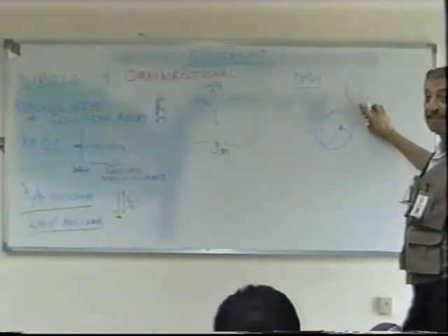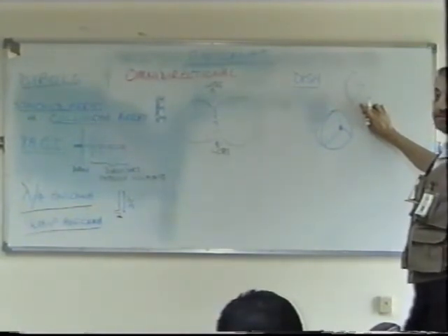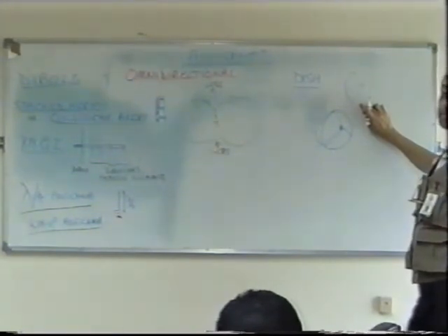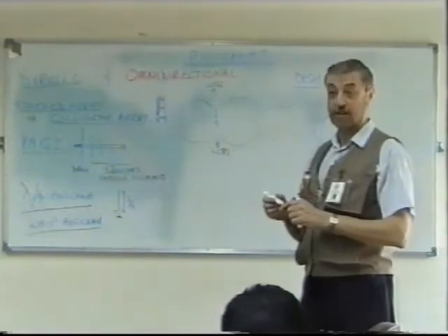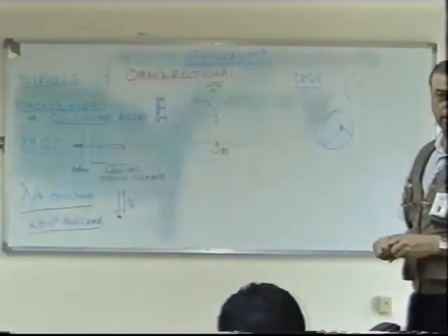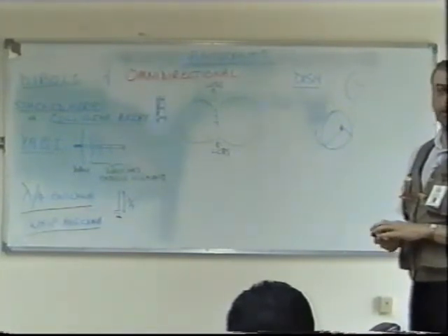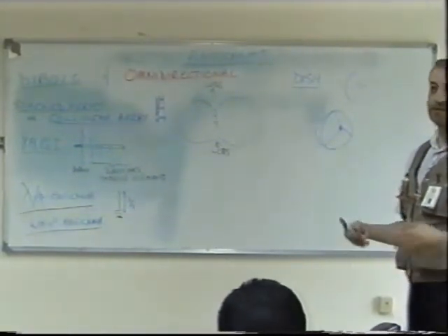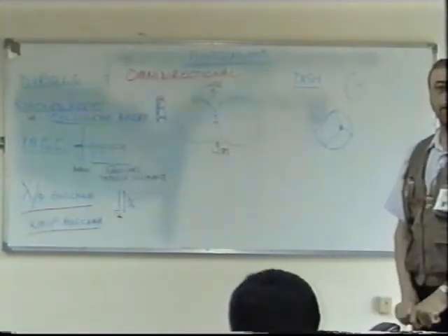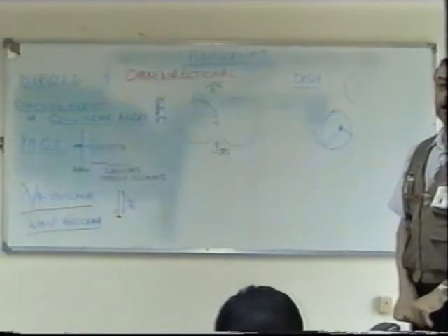What about antennas which collect the signal? Oh, you're talking about the receiving antenna for medium frequencies. They're called sniffers. They're not proper antennas, and they're not as efficient. But because of the high power of medium frequency transmitters, they'll usually work. A receiving antenna is not as critical as a transmitting antenna. Theoretically, it's certainly possible to use dishes for any frequency. But when we're talking about medium or high frequencies, the wavelength's so big it's impractical to have an antenna like that.